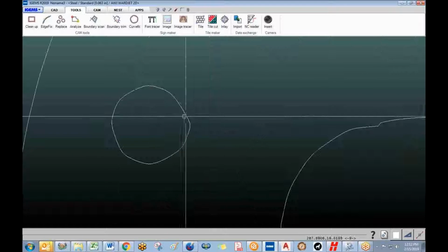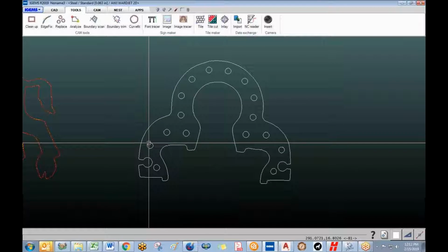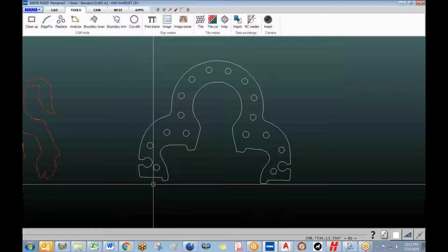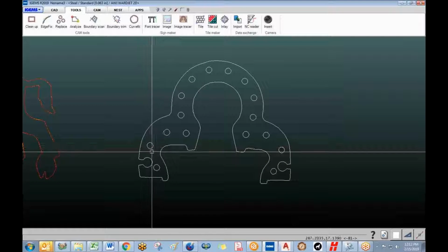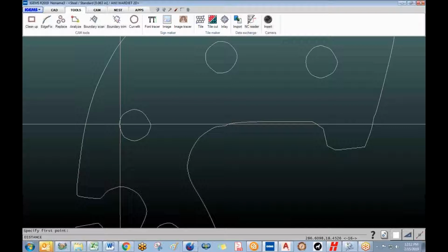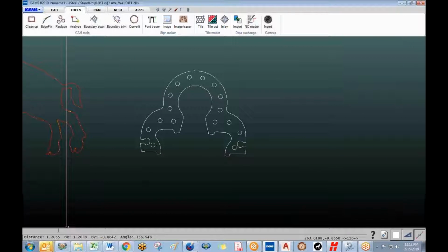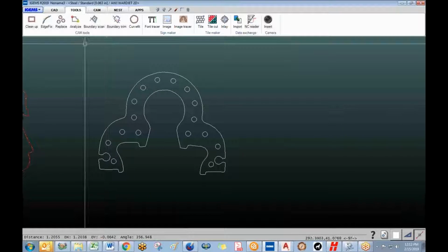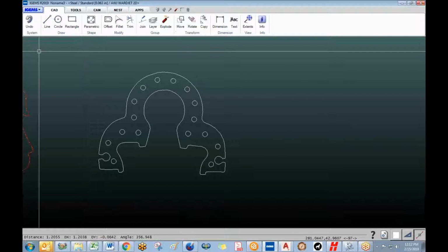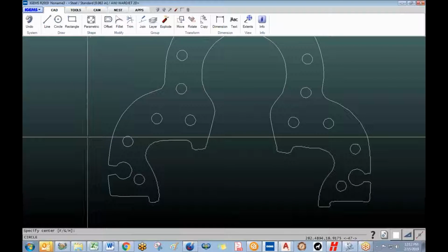And then we've got these beautiful, what are supposed to be round holes. Now, hopefully you either know what the diameter of one of these holes is supposed to be, or you've got some sort of scale in here that you can scale things down appropriately. If I just try to roughly measure what this hole is right now, turn my snaps back on, over here somewhere. So maybe these are supposed to be 1 1/4 inch diameter holes. A couple things I can do here. First of all, I can just draw a circle that's 1 1/4 inches.